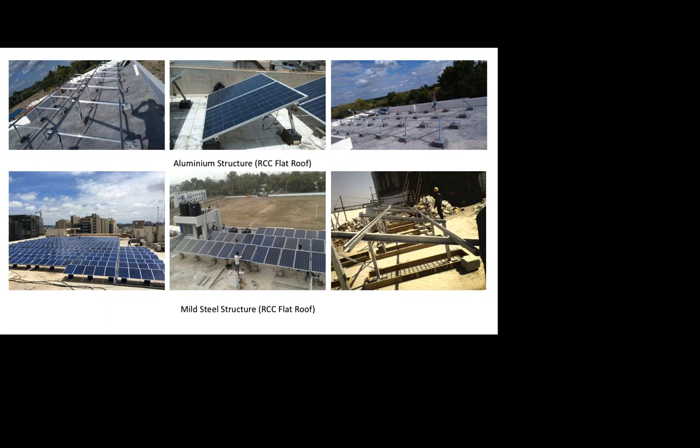You won't see Hilti bolts coming out of the roofs. Where it poses a challenge is while doing the drilling, sometimes you might interfere with the steel which has been put in the roof, or in the worst case, in the case of pre-stressed wires. These are the cables which are laid and then the concrete is done. So you have a risk of drilling away that wire, and in that case it is compromised. But in other cases where normal slabs are there, no specific RCC has been used, Hilti is a fairly good solution.